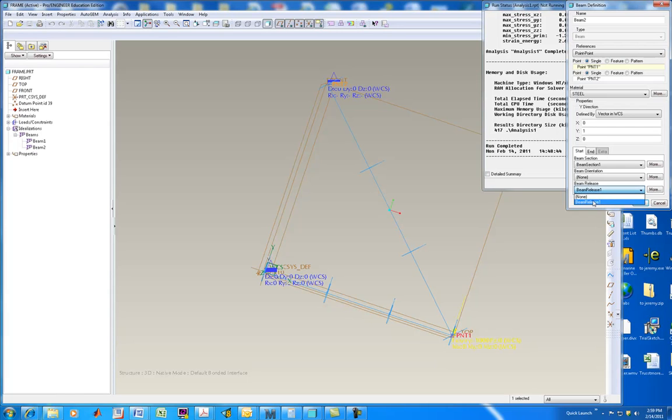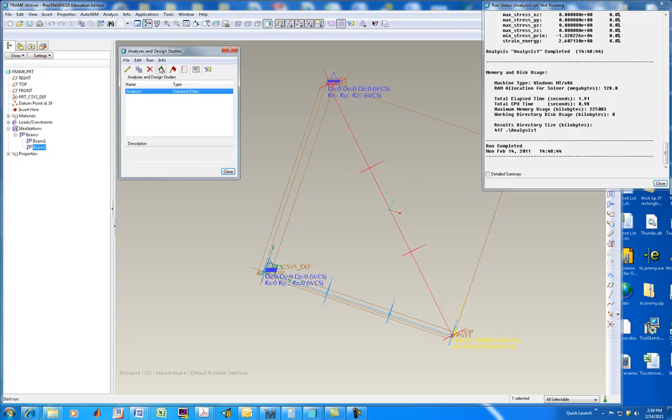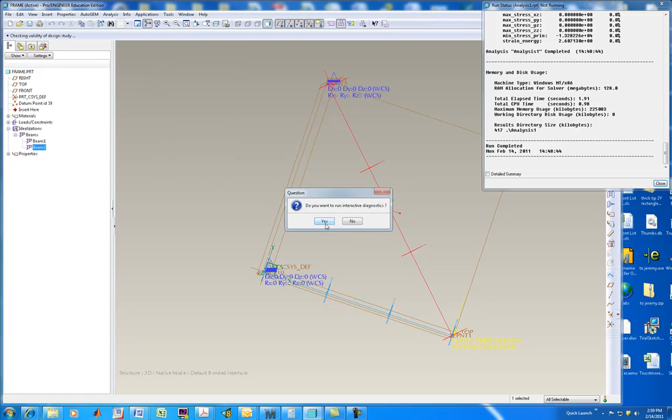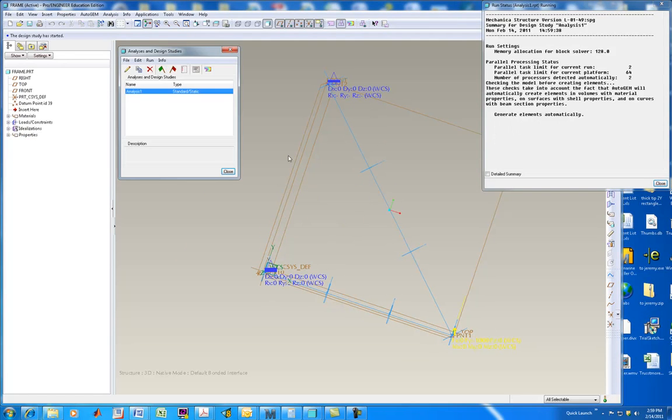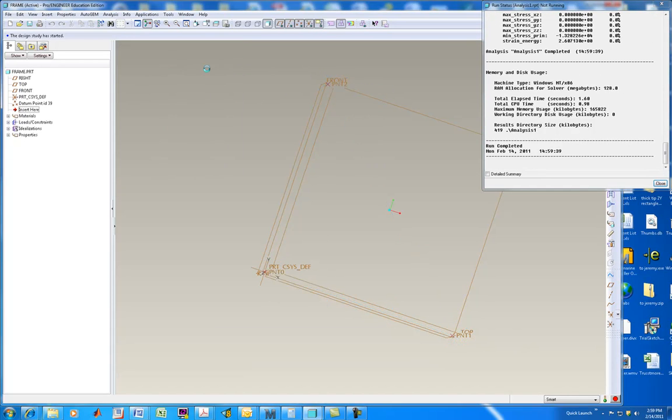I'm going to set this back to none, and I'm going to go to end and set this beam release to beam release 1, which means no rotation about the Z transmitted, or rotations about Z are released. No moments transmitted about Z. So this is in effect a pin joint at this point. I'm going to say OK. We will run the model, and then we'll look for characteristics of a pin joint at that point. We'll see the results happening. The model has run. We'll go look at the results.